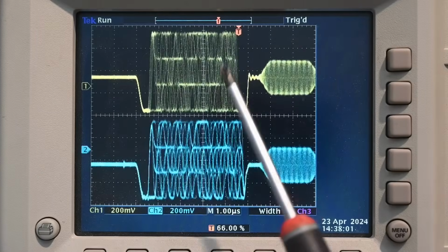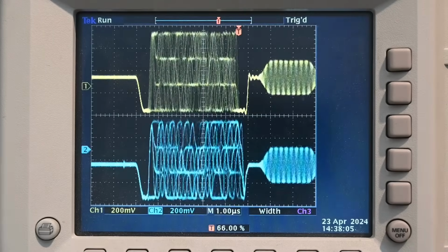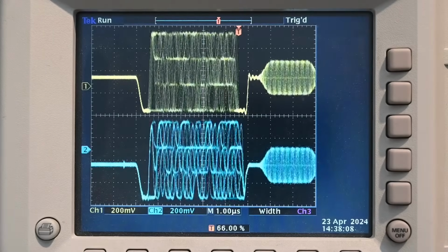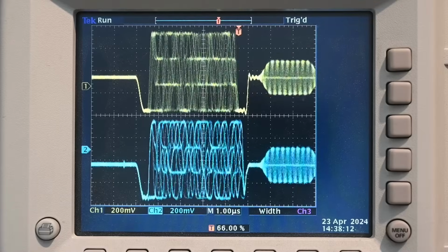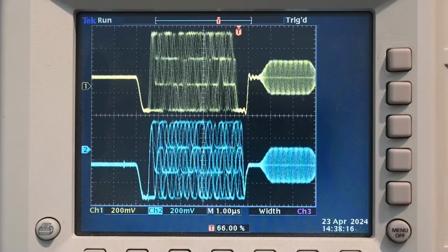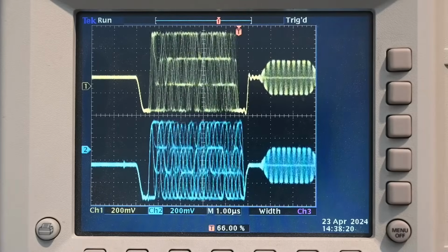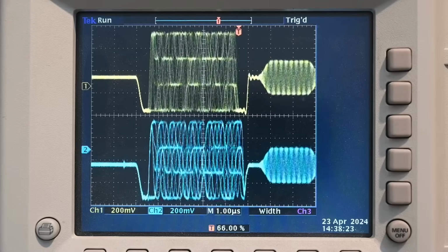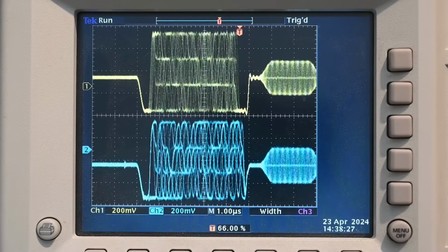In addition to that, because we have the documentation for the system, we know that the actual data inside of here is also likely to be vendor specific. The RE Technology coder encapsulates the NICAM into another frame structure which is proprietary, which contains other control bits, and it even has a scrambling mechanism on top of it. The odds that TVT will have done exactly the same thing are pretty much zero. So anyway, there you have it. The two systems are definitely incompatible. It's not just that nobody ever tried to plug them together.